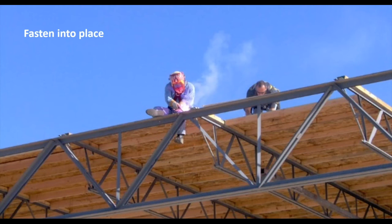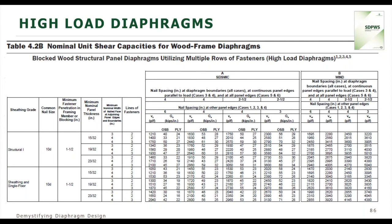And then you have 2 framers on the roof that are tethered off for safety. And one is there to weld the bar joist to the girder. And then the other framer is nailing off the diaphragm to that common framing member. So they can really construct these real fast, and that's one advantage of having these panelized roof systems. And the advantage of using high-load diaphragms is you have a much higher capacity for these high-load diaphragms.